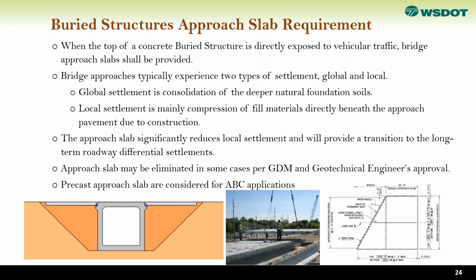One thing also specific to us for those buried structures that are exposed to the roadway, we are using approach slab. And this approach slab buried structure typically experience two types of settlement, global and local. The global settlement is a consolidation of the deeper natural foundation soil, so this area here.